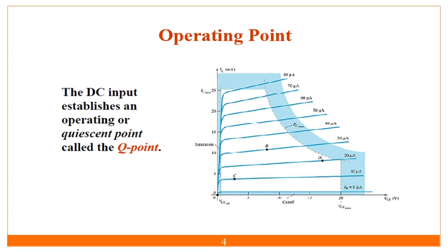So this portion which I have drawn over here is called the cutoff region. Cutoff means what? In this region your transistor will act as an open switch, which means what? Suppose this is the switch and this circuit is like this one. So open is now what?